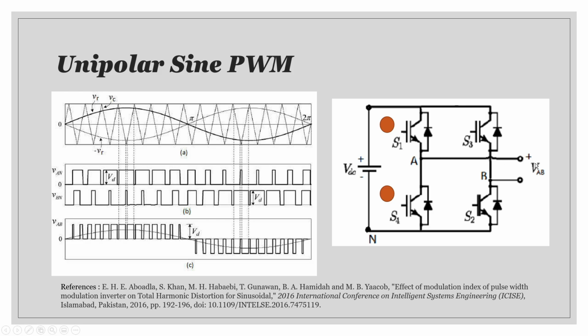It's actually okay to freewheel through the diode of the MOSFET, but if the load has a high current, it will cause more losses on the diode and make the MOSFET hotter.